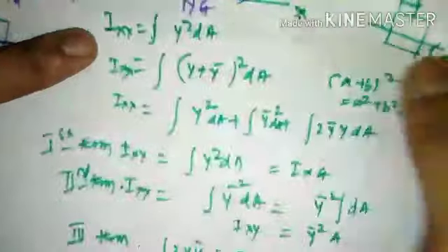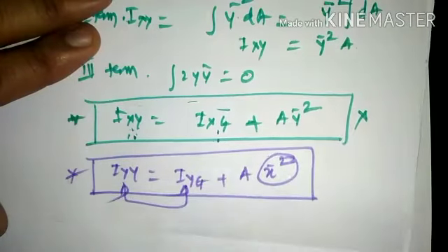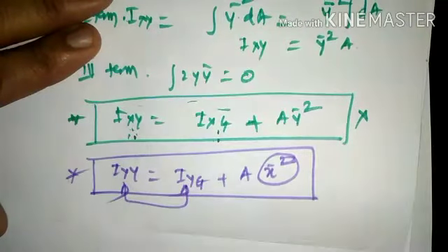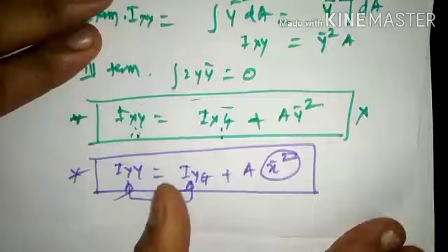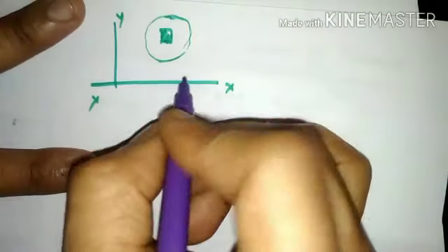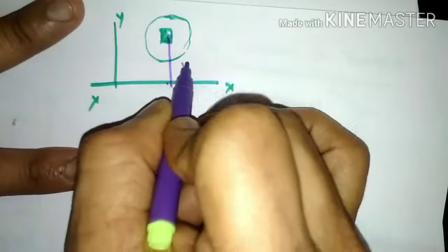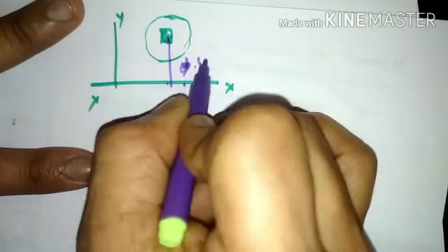This is from the second principle. When we integrate and then separate it, this is the solution that we get for Ixx and Iyy. So the perpendicular axis theorem says: consider an element which has been placed in the x and y plane. The location of this particular elemental area along the y direction is nothing but y.